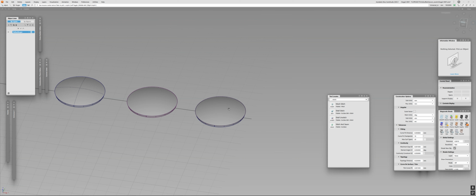Well, anyway, as a conclusion, guys, the right way to give thickness in Alias is to use the offset command. The specific algorithm within can vary based on your situation, as I showed before, but all of them can easily fail one way or another, forcing you into manual labor. So it's always a pain. It will always fail one way or another, and it will force you to intervene, in most cases manually. And as for the golden rule, there is only one. Always offset inward, not outward, as an offset surface will always be worse than the original. The outer shell is more important in terms of its quality than the inner one.